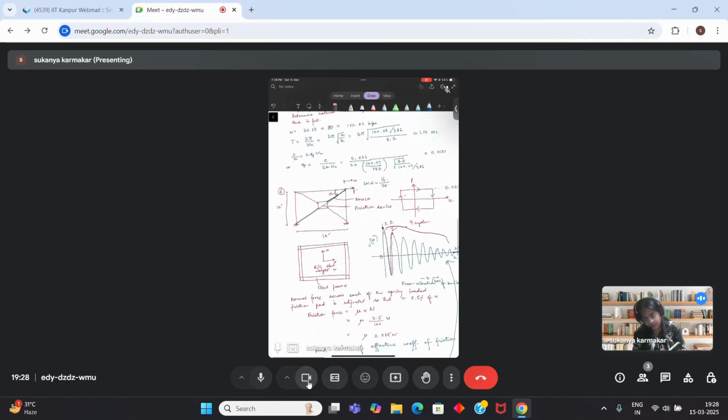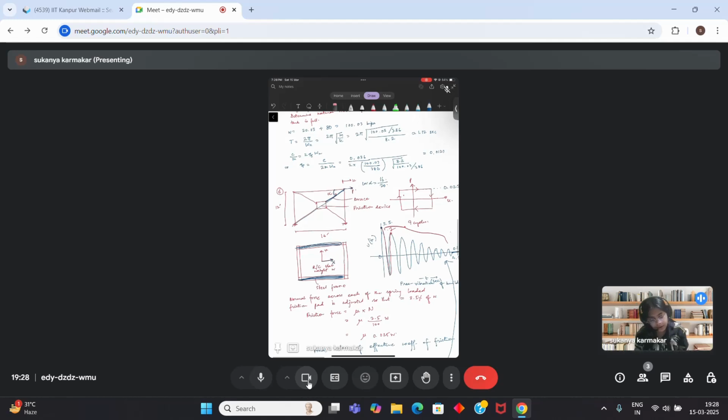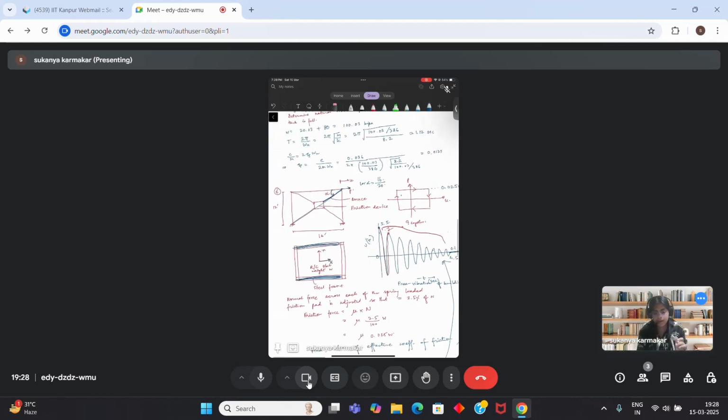Due to bracing, each friction device has four bracing, no? But you have two frames in the x direction. So you have one frame which you are considering, this frame and this frame, since the free vibration of the building is along the x-axis. So there are two frames which I just highlighted.